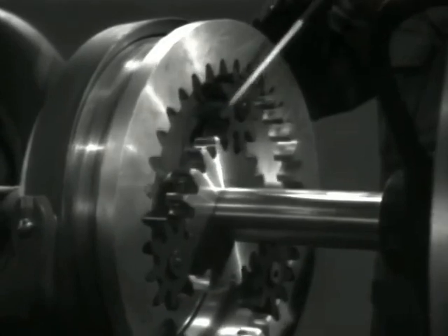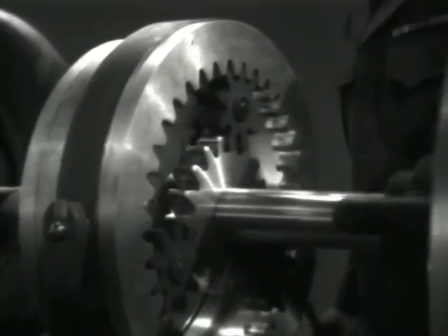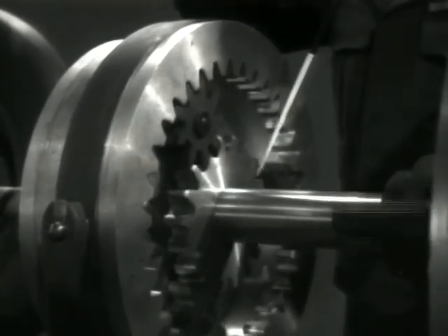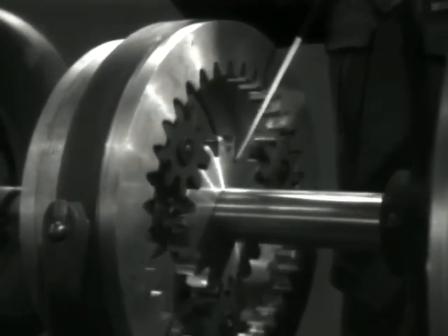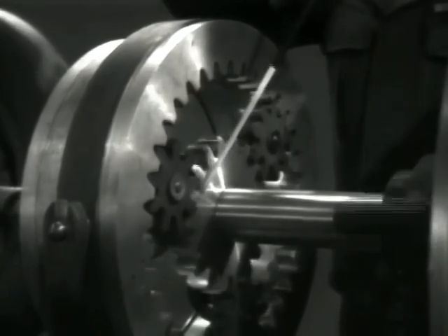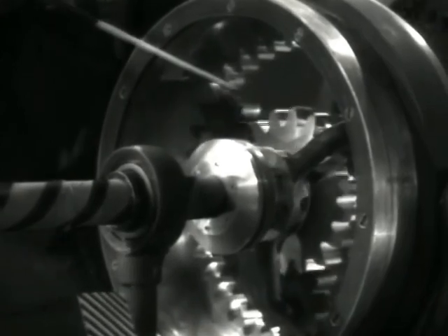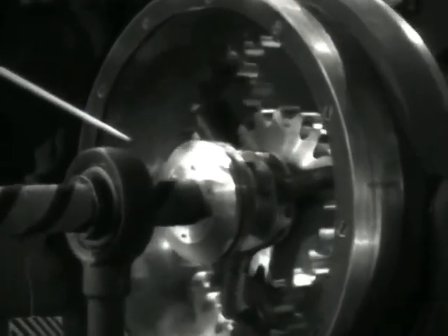This reverse movement of the intermediate ring gear is transmitted by this connecting shaft to the sun gear of the reverse unit. By making the ring gear of the reverse unit reactionary, the planet carrier becomes the output and follows the direction of the sun gear, which is driving. The reverse planet carrier transmits the reverse through the output shaft to the wheels.